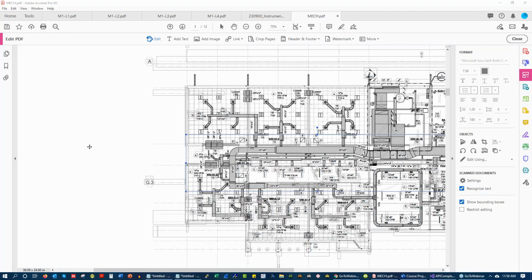If you use the same sequence for every rooftop unit or every VAV box, then in theory the controls contractor, if they're the same one or at least the same brand, should be able to take a common code base and real quickly implement code across your buildings.